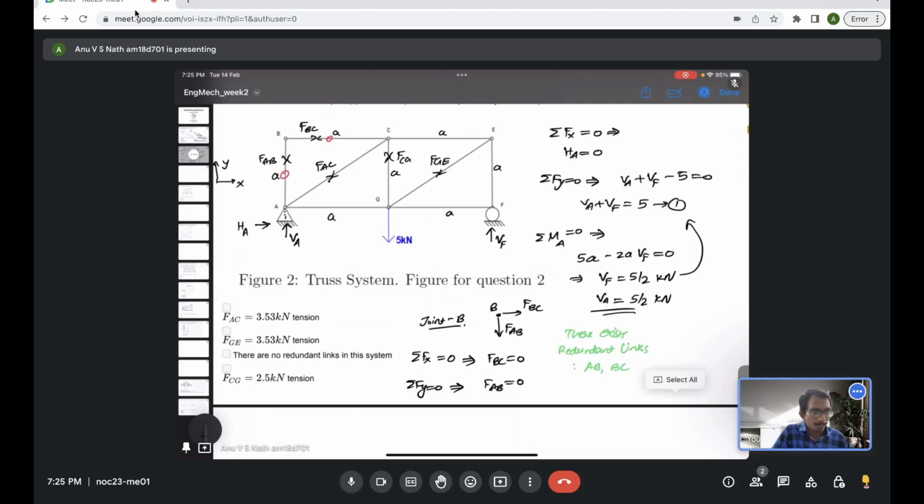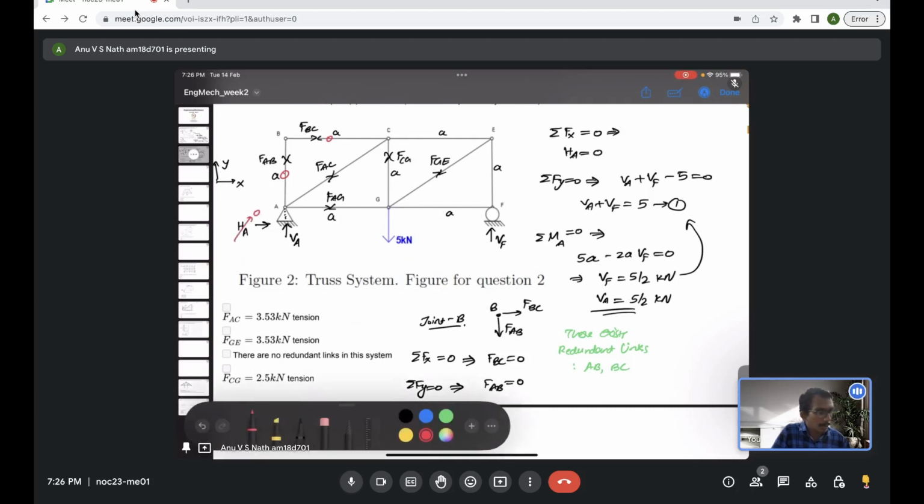Now we know FAB, FBC. So earlier, if you think about joint A, you have four unknowns, right? FAB was there, FAC was there, and in this link FAG will be there. And VA and HA we already evaluated. HA we have evaluated to be 0, and VA we already know.